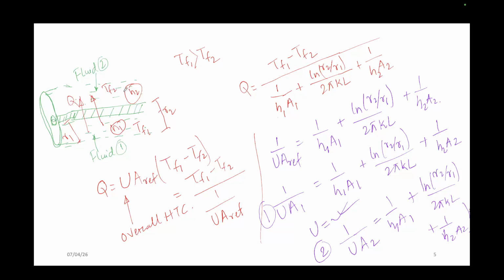Similarly, when a heat exchanger works on a certain fluid for a long period of time, what will happen? The tube surface is covered with certain types of material, an insulating material, which is also known as scale or foul. So what do you think will happen if the tube surface is covered with certain impurities or dust particles? If its thermal resistance increases, what will happen? Yes, good. That I will show in the next one.